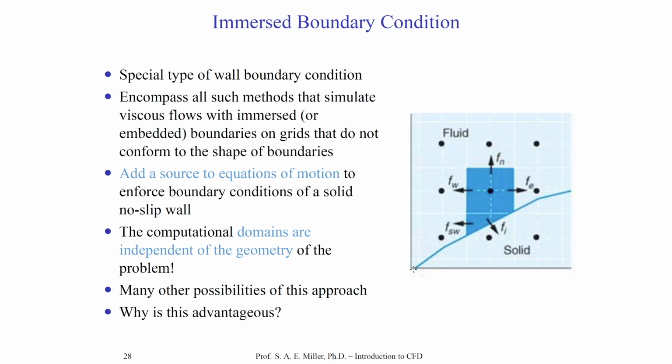You can imagine there's a major advantage of this approach. We can just use structured grids and not ever worry about resolving the geometry of the vehicle. We would only need to impose through mathematics in the solver equal and opposite forces and energies within the equations of motion.